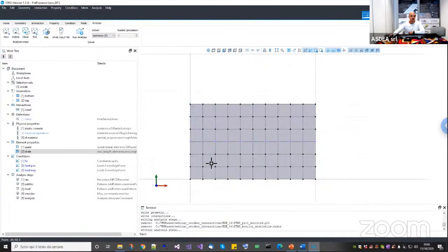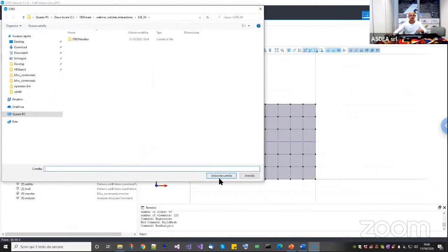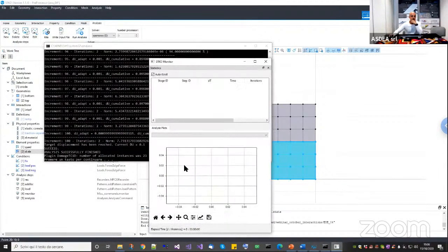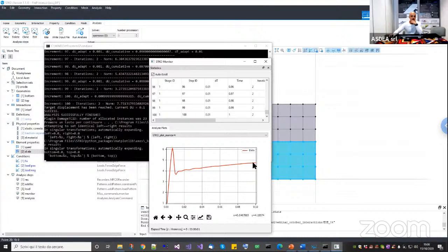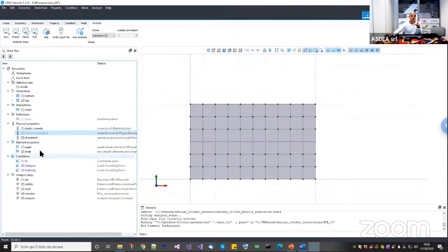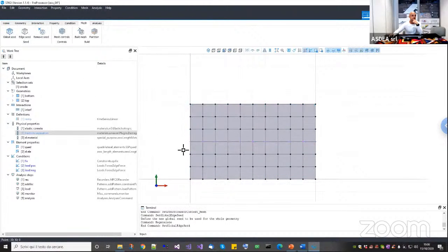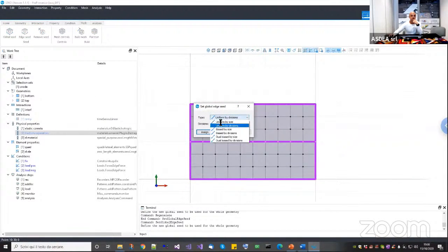Now I do the same, refining my mesh, and you will see that the result will be the same. So just to remember the result, it goes to 6. Yes, then it goes down and then up again, okay? Now let's see, if I don't change anything to my material, just because I use the distributed, when I go to mesh and I change the mesh size, for example, uniform by size, before it was 1, now 0.5. Not 0.5, sorry, it is too fine, it was simply 5.